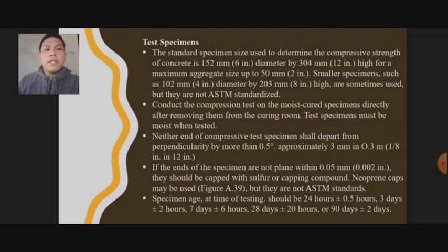The specimen age at the time of testing should be 24 hours plus or minus 0.5 hours, 3 days plus or minus 2 hours, 7 days plus or minus 6 hours, 28 days plus or minus 20 hours, or 90 days plus or minus 2 days.